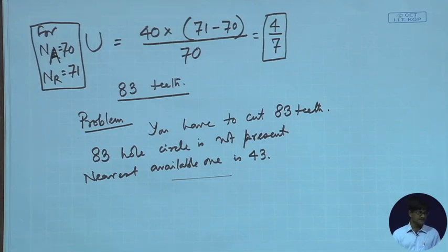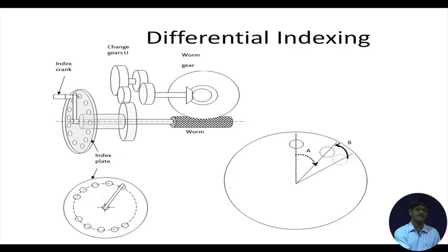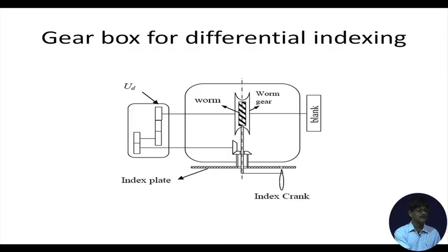So, I will be giving you more problems of this type when we discuss further. Now, for a quick look at what we have discussed, so that our doubts, if any, will be cleared. For those people who have had trouble following the three-dimensional pictures, I have tried to give the explanation in a flat two-dimensional drawing. Let us have a quick look at it. This is our index crank. When you are rotating the index crank, this is the shaft of the index crank which goes right through to the worm,